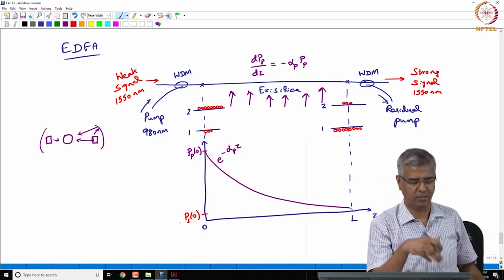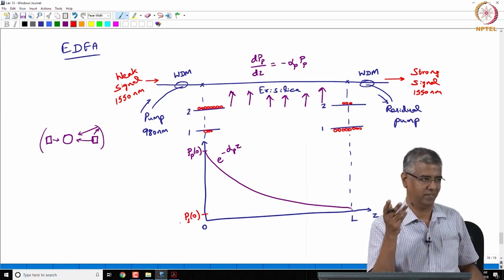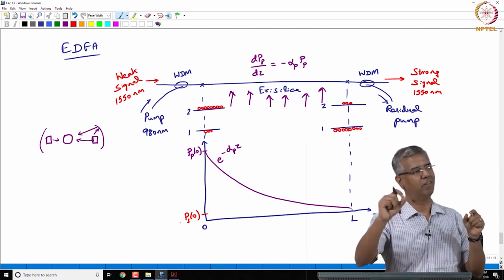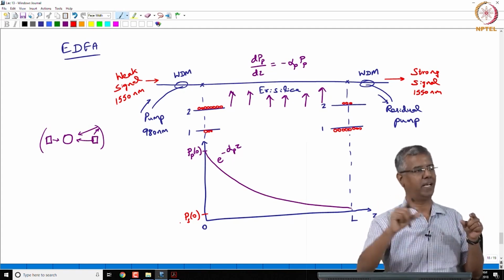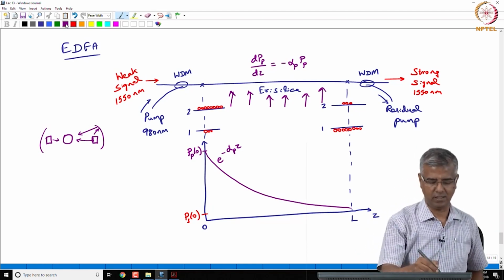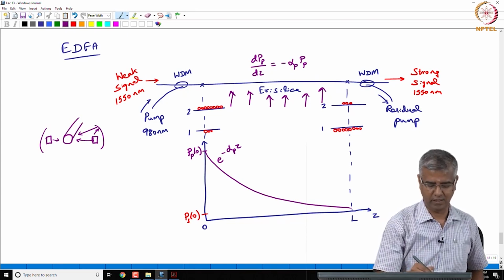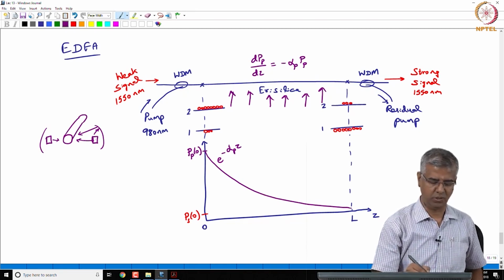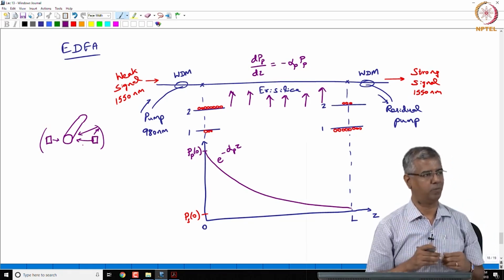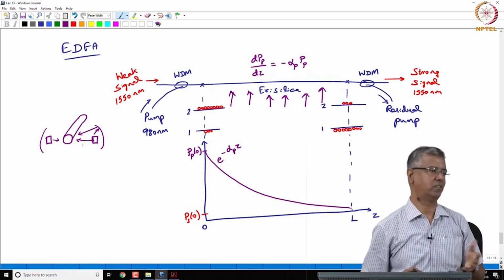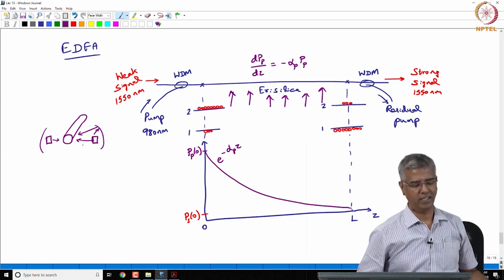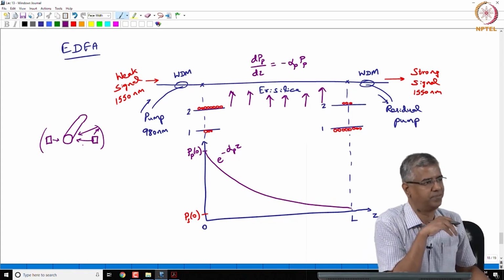Compare that to a rod, which can be a few millimeters thick. In that case, and it's a relatively short rod, you can actually have these pump diodes stacked along the rod, and they are all pumping like this. So, in this case, the rod in 3 dimensions would look like this, and you could have mirrors on either side, and then the row of pump diodes which are directly pumping the rod. So, you would actually have fairly good efficiency with which you are absorbing all that pump radiation.